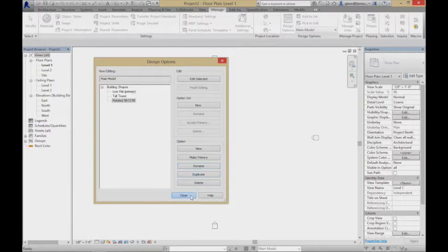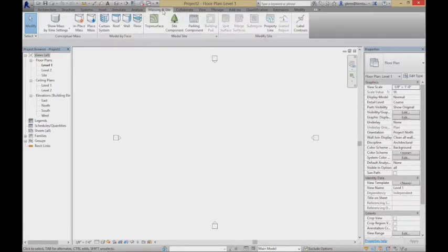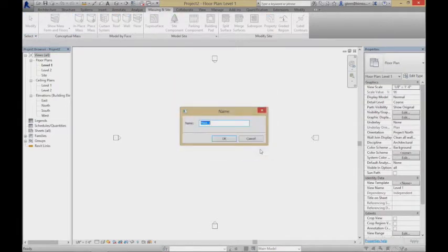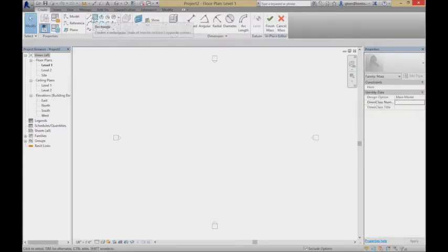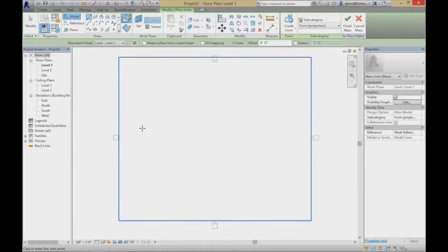And how we will use this is as follows. Let's close that up. What we often do when we're modeling a site is take the main contextual buildings, the ones that are all around the building that we're going to be designing, and make mass models of them just to give us a little bit of site context. We can think about shadows and how those other buildings might affect them. So I can create a mass, and I could make a bunch of individual buildings or put a bunch together. I'll call it existing buildings. Not spelled very well, but I won't worry about that. And let's say, for example, I was doing something like the SEQ quad.